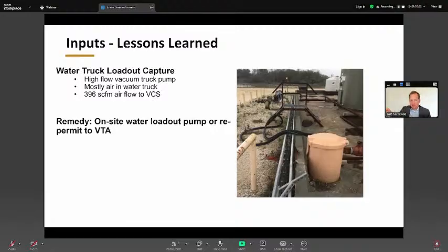But they do a vapor bounce back to the tanks to balance out that tank, so they're not venting hydrocarbon that's with that water, such that you're sending a huge rate back to your tanks from that vacuum pump. And that can cause a significant overpressurization. It tends to not be combustible, but as soon as you open that tank, you're going to be letting all your oil flash come off as well.